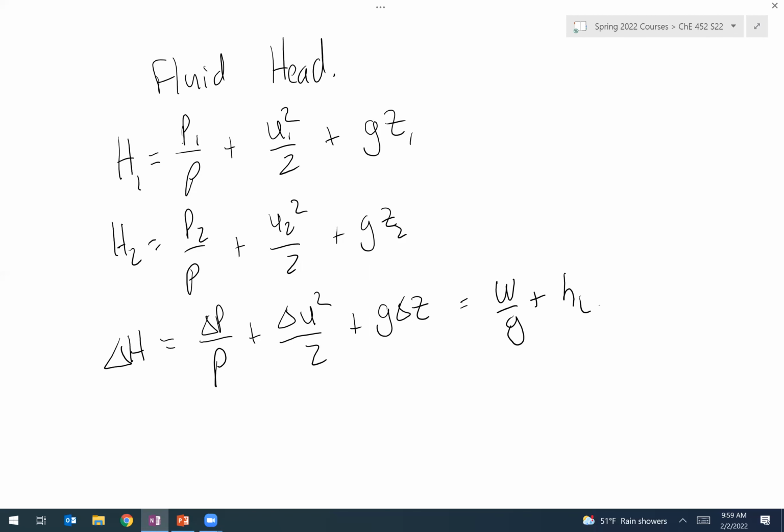And so the moral of the story is, if I'm wanting to transport a fluid, I have to ask myself, what is the energy associated with the fluid at 2 points? And what is my anticipated head loss, such that I can determine a necessary energy input such that the fluid can travel from one point to the other.